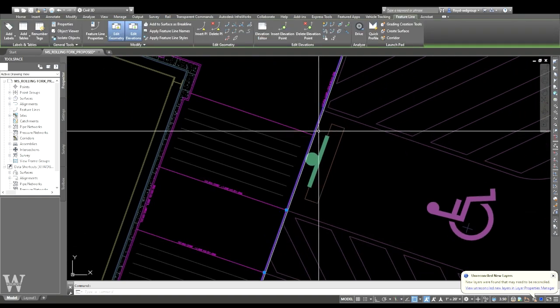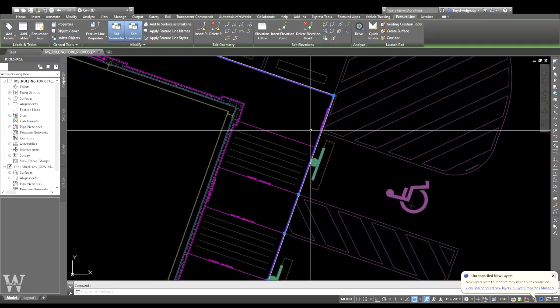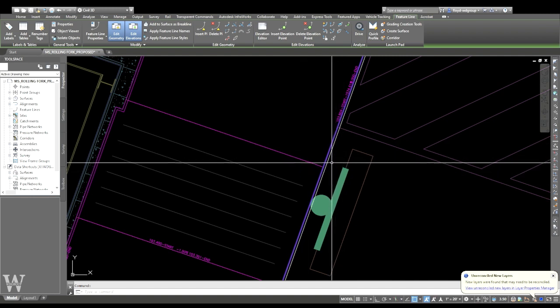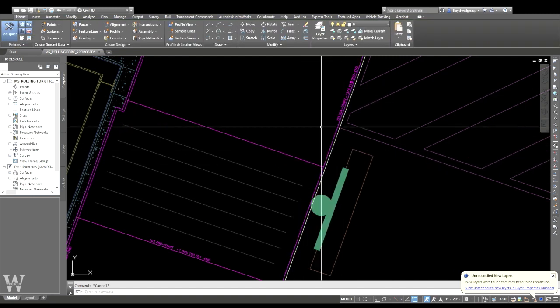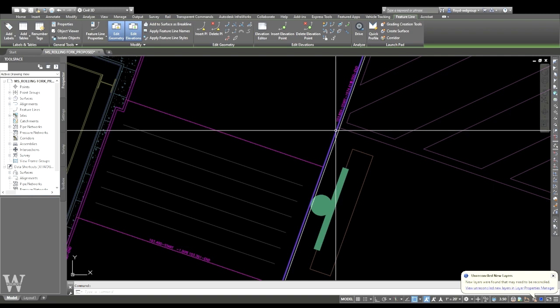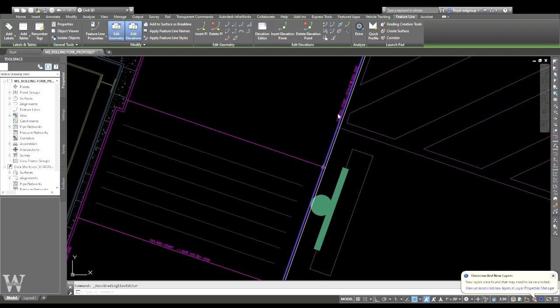Okay, so what happened was, you see right here, we didn't put a PI point right here, so we need to add one. And so you see it's not there. What you also see is this is that point. So if I go somewhere else, if I click on that grayed out, what that says is all these green ones here, that means, hey, that's a real live point and I can move that. That says, hey, you got a point that another feature line's crossing us and it's giving us this, so it's forcing us to be this elevation. Is that what you want to do or not?